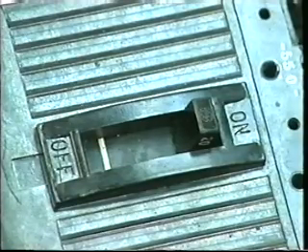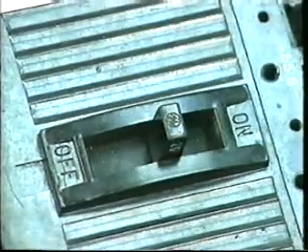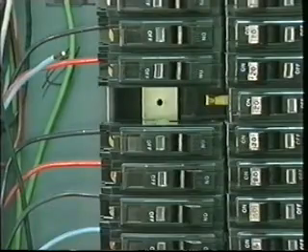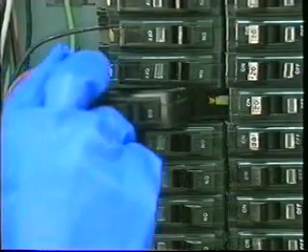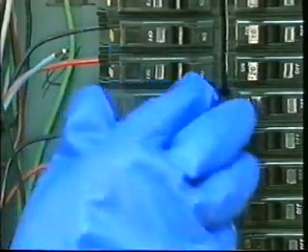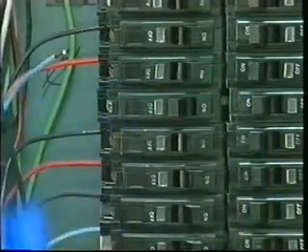Thermal magnetic trips are best suited to the majority of general-purpose breaker applications. They trip with time delay, where an overload occurs, but trip instantly on heavy short-circuit currents. The final component of a molded case circuit breaker is the terminal connector. The function of the terminal connector is to connect a circuit breaker to a desired power source load.